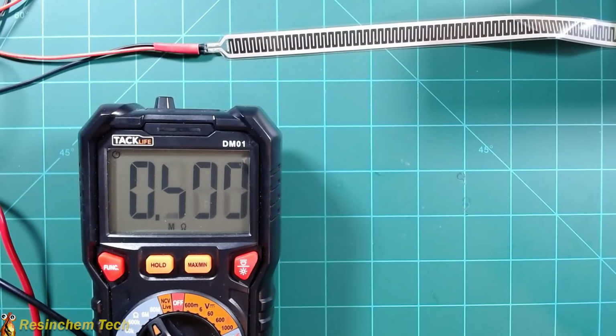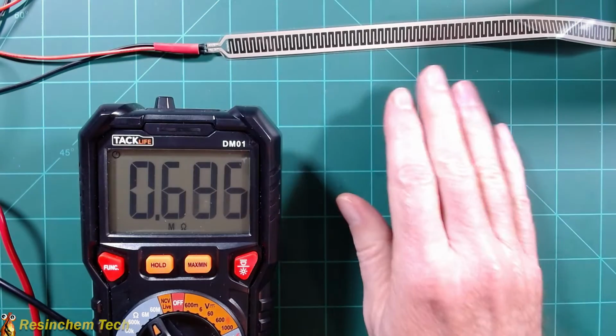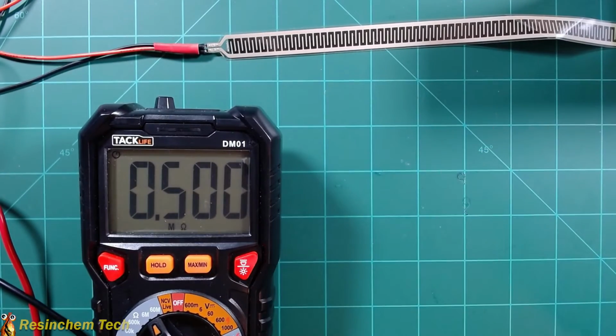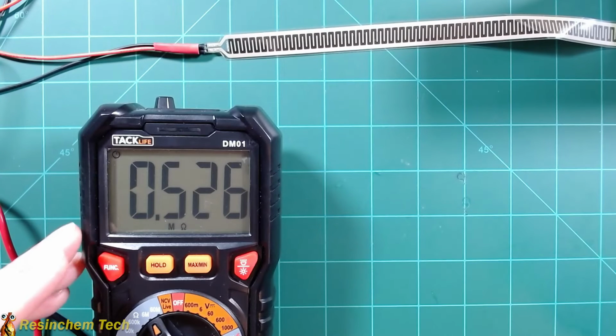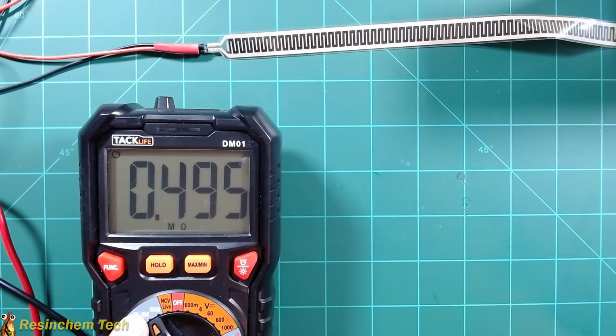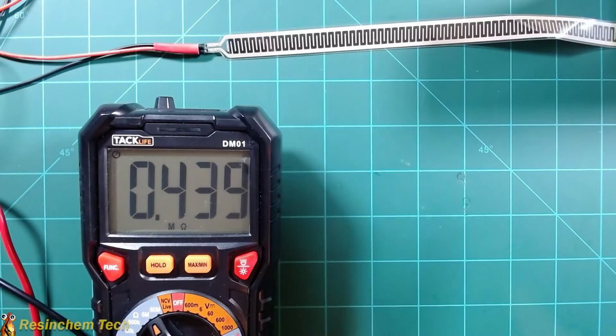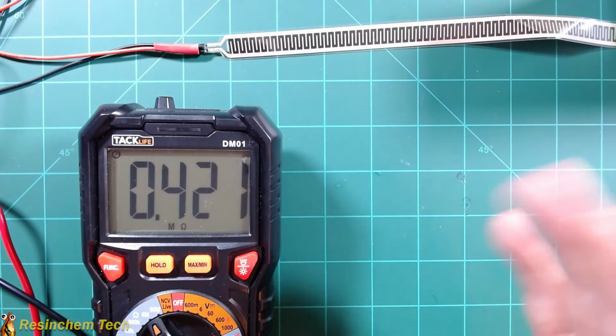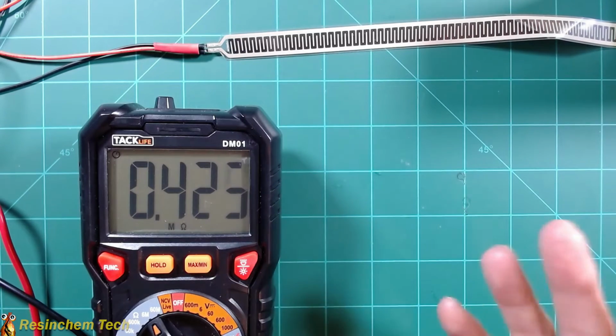To get your starting resistor value, what you'll want to do is take your strip, go ahead and install it under your mattress temporarily, and hook it up to your multimeter set on ohms. We need to get a starting resistance value with the bed unoccupied versus occupied. So I've got a little bit of weight sitting on here, otherwise it would just be out of range, but your readings will be completely different.